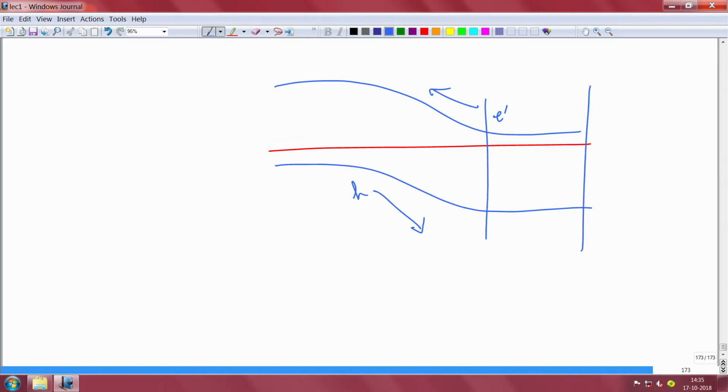this region which is supposed to be a neutral region is not strictly neutral, because there will be some field, some voltage that will drop. There will be a very small field that will exist here, and that is why these are called quasi neutral region. So, it is not exactly neutral, and there is a very small field that exists there. Okay, there is a very small field compared to this slope, that slope is almost negligible. So, we write it flat, but there is a small field that is here, very small field, okay, and it is called quasi neutral because some voltage is dropping here.